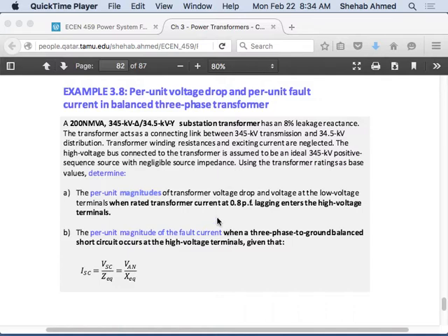So on the high voltage side, you have your source, the impedance of the transformer, and a short circuit. They're asking what the short circuit current is. Initially you had 1 per unit, rated current was going through. Now you expect something much higher. Rated current means you had a load on the secondary side, transformed to the primary side. I don't care about that, because they didn't ask about it. They just asked for the transformer voltage drop, so you have current and you have the impedance.